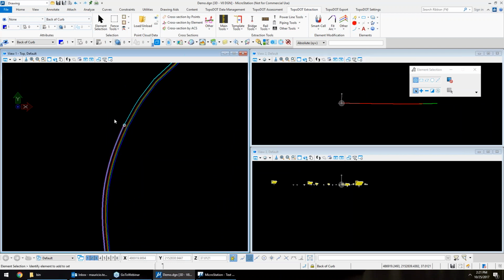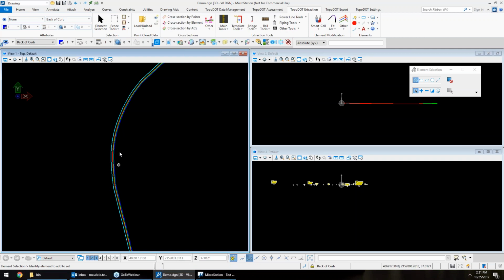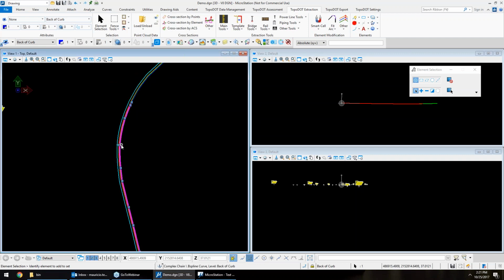And then if I go ahead and accept that, what it does is that area that I told it to, it sticks a B-spline in there, but still retains it as a single line. So you don't have to reconnect it or anything like that. Now, some people don't like actual B-splines being used in there. So the other option, let me go ahead and undo that.